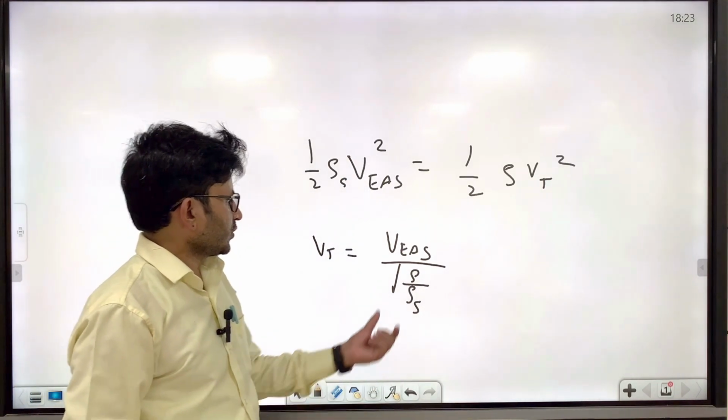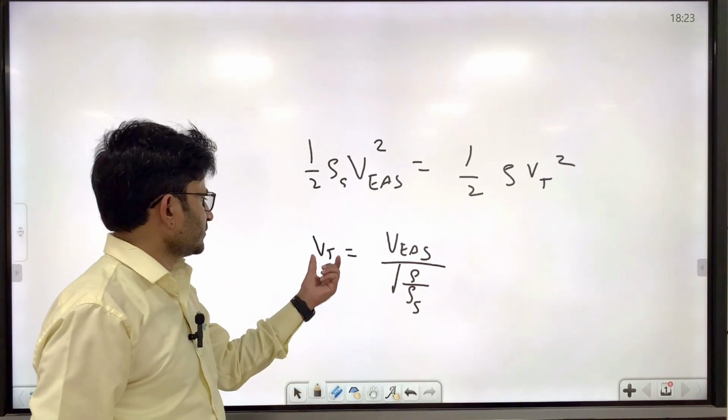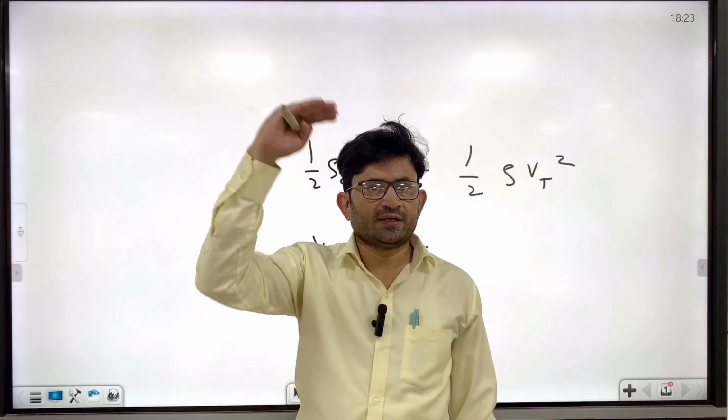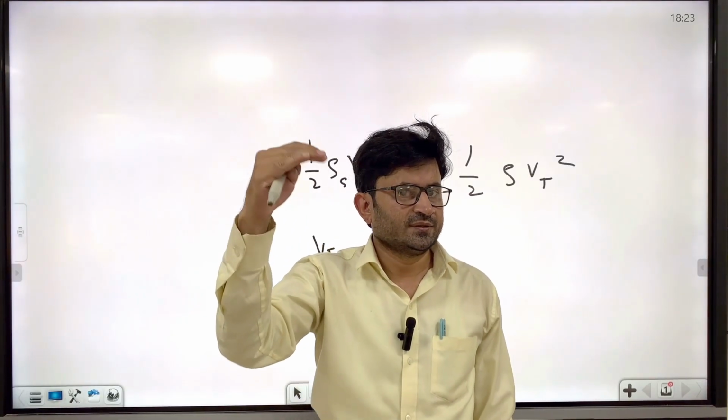So rho decreases with increase in altitude, so the true speed will increase. At each and every altitude the trim speed will change, right?